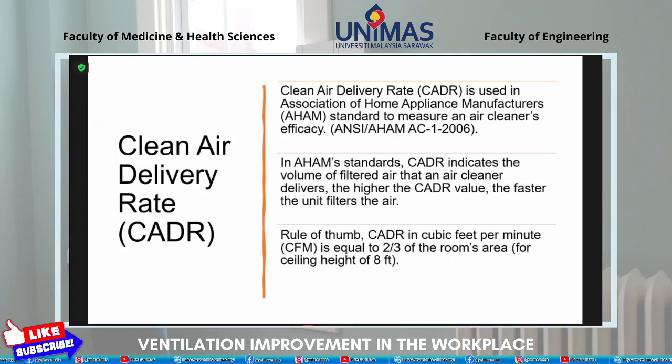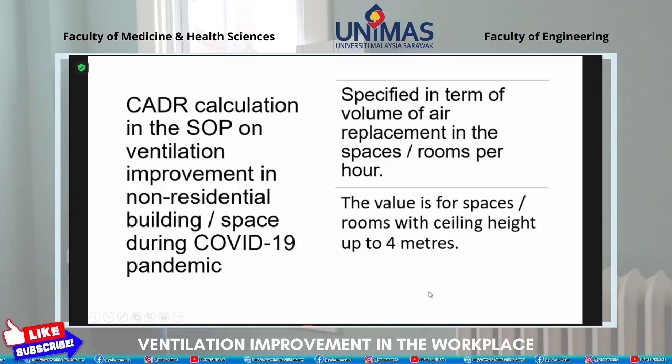Yeah, about 8 feet. But for offices, definitely our ceiling height is much higher, maybe up to 2.83 meters and so on. So it's no longer 8 feet. 8 feet is about 2.4 to 2.5 meters only. So we decided that instead of using those terms, it doesn't really differ much, we still want the flow rate. Instead of using that kind of calculation, we try to follow the standard, or ASHRAE standard.